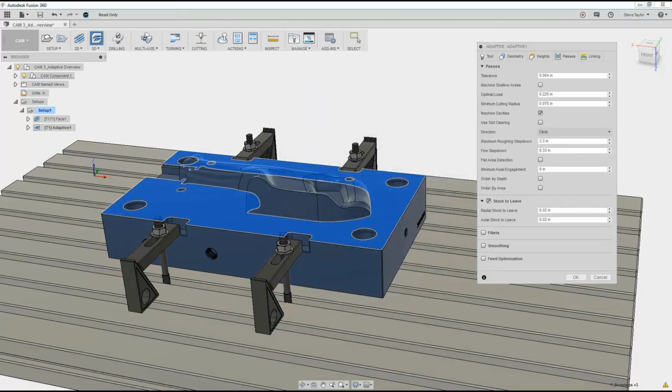This will also ensure that we are not just using the first quarter inch of the flute. When you're machining, if you're not careful, you might have a tool with a long flute length, and if you're only cutting on the very bottom of that flute length, that's where it's going to wear, and you're going to get uneven wear.